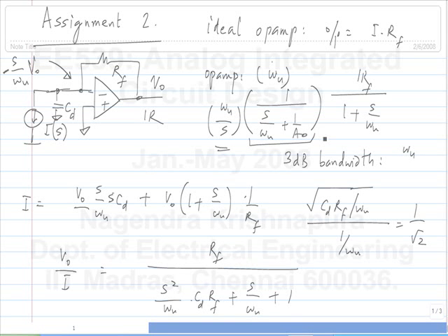Okay. Because the DC gain really matters only at low frequencies, at DC, unless the DC gain happens to be really small. So, most of the times you can safely do all of this high frequency analysis regarding stability and so on, by ignoring the DC gain and assuming that it's an ideal integrator. But you should use the same unity gain frequency as was there. So, you assume a model with only the unity gain frequency, ignore the DC gain, set the DC gain to infinity, you will get more or less the same answer.